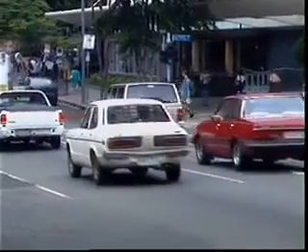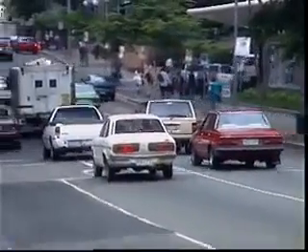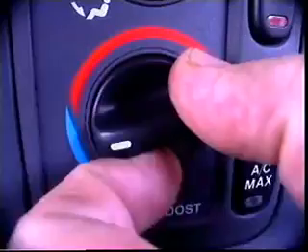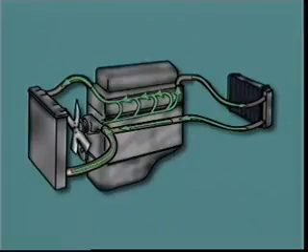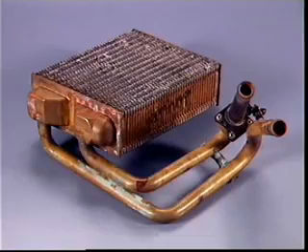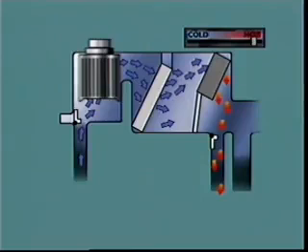In internal combustion engines, much of the heat generated is lost to the atmosphere or wasted. Some of this heat can be used to heat the incoming air to a comfortable level when required by the vehicle occupants. Engines that are liquid-cooled direct heated coolant to a heater core to heat the air. The heater core is a small radiator consisting of tubes, fins and tanks. It is mounted under the dash panel inside the air plenum chamber, where air can be passed across the core fins and into the vehicle interior.